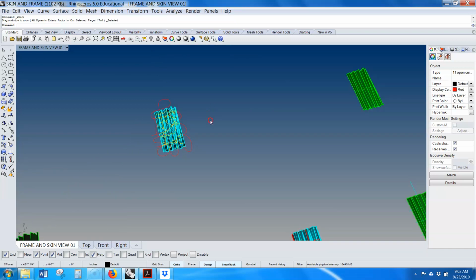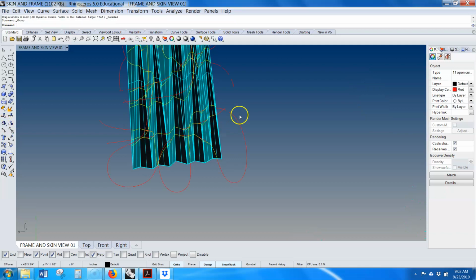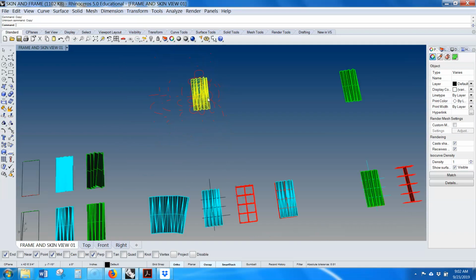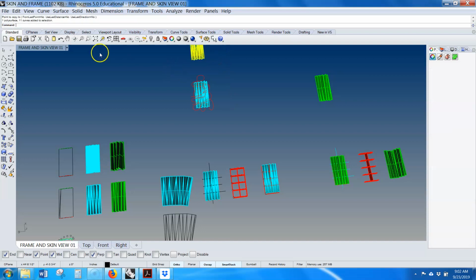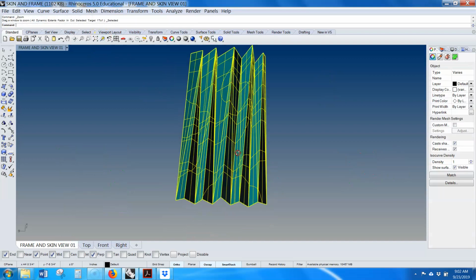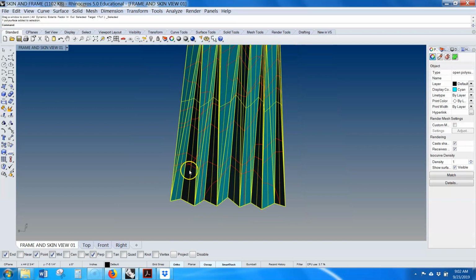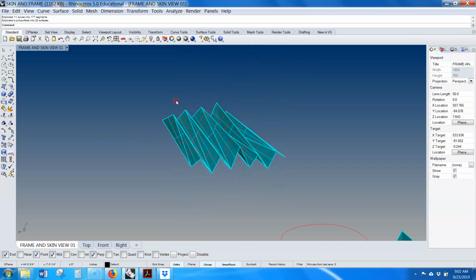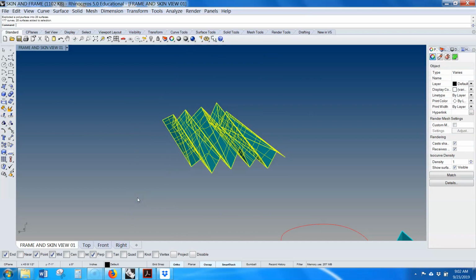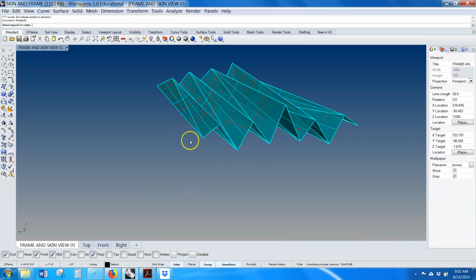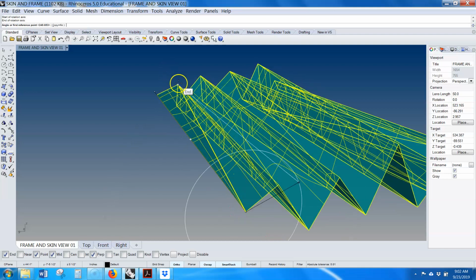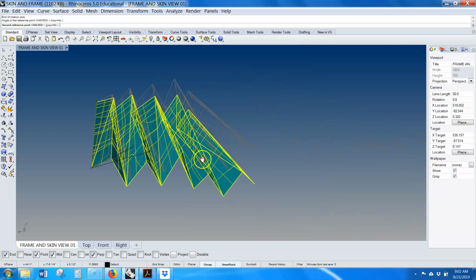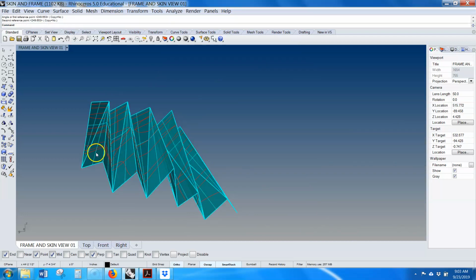So anyway, if we want to do that, okay, now we want to flatten this and laser cut it, right? So the way to do this would be to explode that. Right, and so we can select it all. And now we can do rotate 3D. So this is the manual way to do it. Like, you all will be very good at just 3D rotating things flat by the end of the semester.